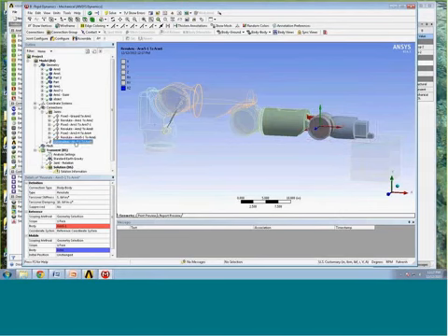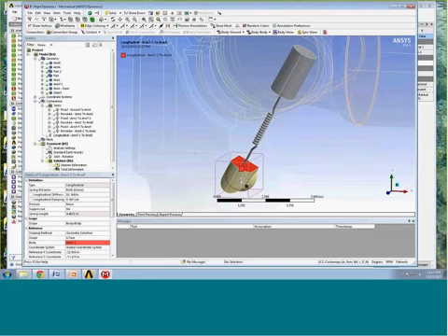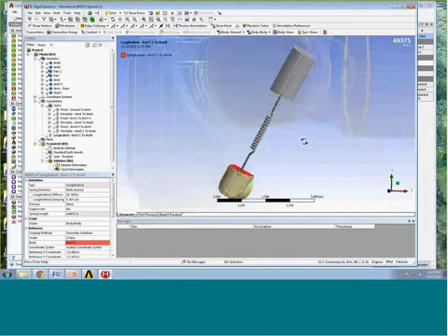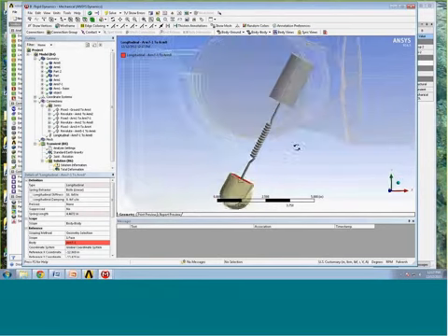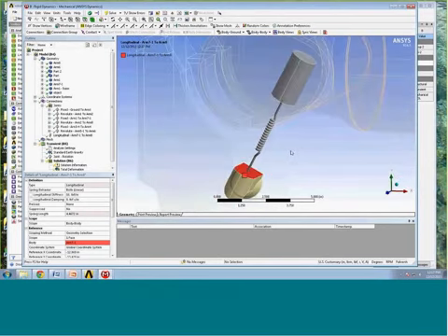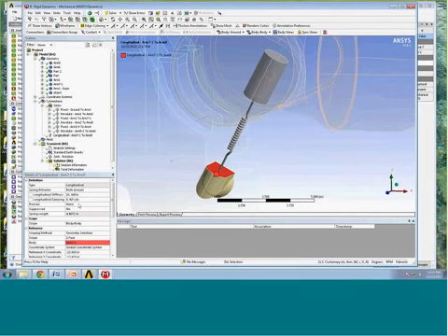Okay, I also have a spring here which attaches these two parts at the actuator location. I don't have the actuator explicitly modeled in here, so this spring is inserted simply to stabilize the two parts that it's attached to. And you can see these surfaces that are colored. These surfaces that are colored are the two end locations that the spring is attached to. And you can assign a spring stiffness or a damping, so you can include a damper in here as well.